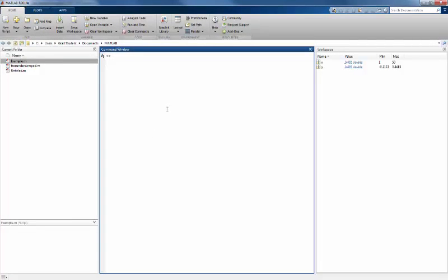Alright, so to use this ginput command, we first need to start with a variable. So we'll just call ours [xp, yp] in brackets. And that's going to be equal to ginput. So also what we can do here is we can follow this command with a pair of parentheses and a number. And that number specifies the amount of points that we can pick off of our graph. So let's just go ahead and say 3.